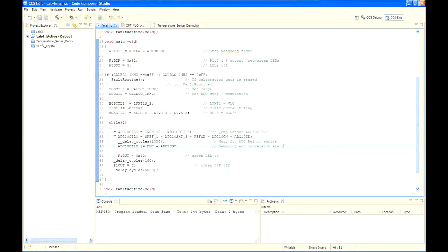So let's examine those code lines one at a time to make sure they're doing what we need them to do. You'll need to open up your user's guide and header file for reference again. It might be easier to keep the header file open in the editor for reference. So first thing, let's change that ADC10DIV_3 to ADC10DIV_0. The ADC10 control register 1 is one of the ADC10 control registers.